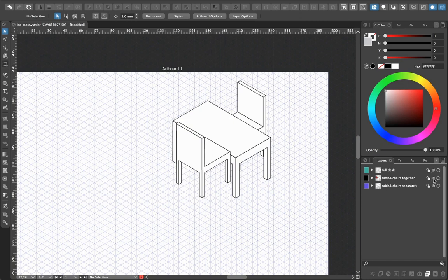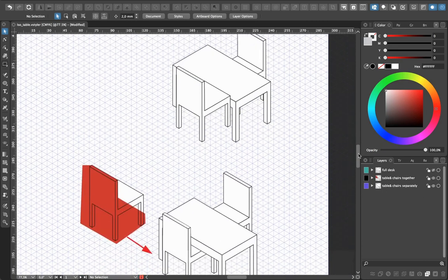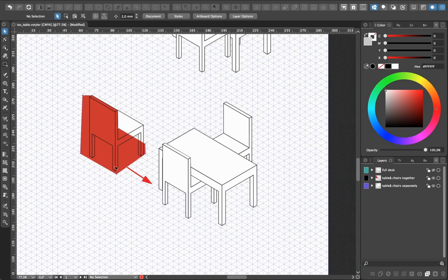So that's when you use a clipping shape. Here I put it in red. Of course you don't put it in red, you just create this shape as a container. You take your chair from the library, you copy and you paste inside the container, and all the parts which are common to both, meaning in that case the red part, will be visible, and everything from the chair which is outside of the container won't be visible.